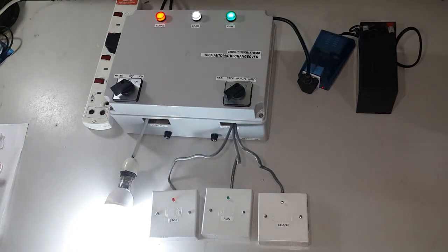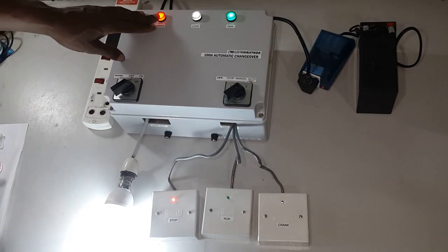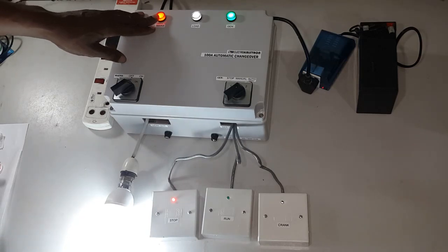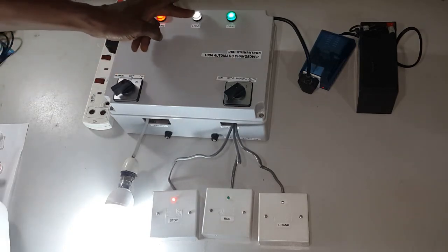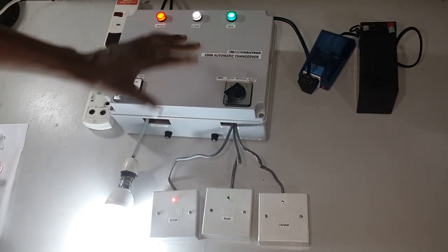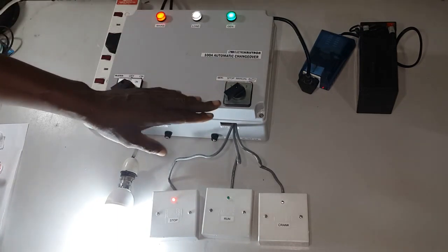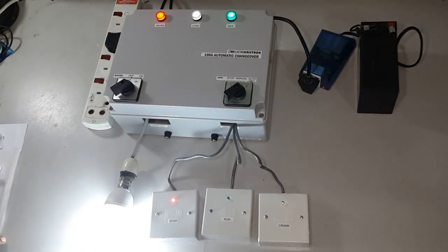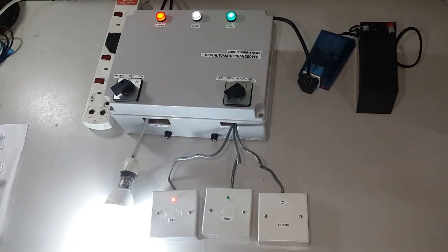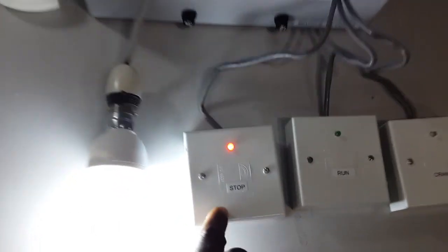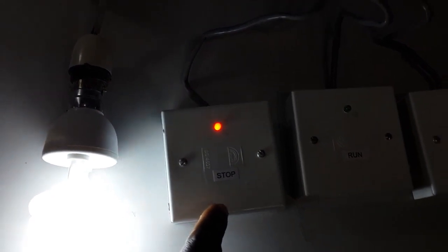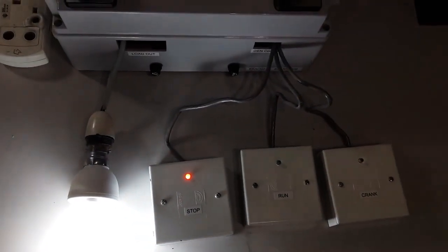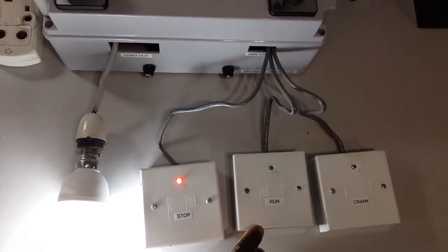Now first thing that happened was that the mains power, after some initial delay of a few seconds, typically 7 seconds, the power was transferred to the load, and then the command to stop the generator came from the ATS, and the generator indicator for run went off. Now we see that a new indicator has come up, the red indicator for stop. Now this is for those types of generators that don't use the run command.